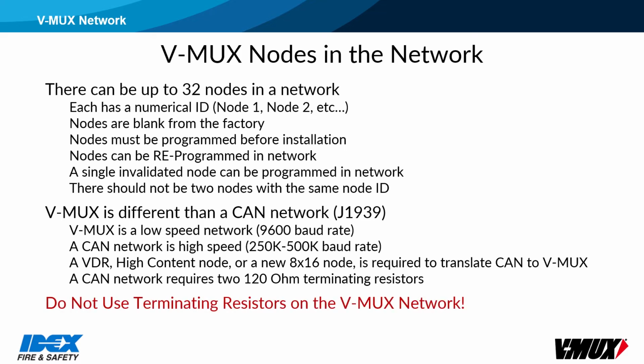It's very important that terminating resistors are not used on a V-MUX network. CAN requires the resistors, but they can cause problems in V-MUX networks.